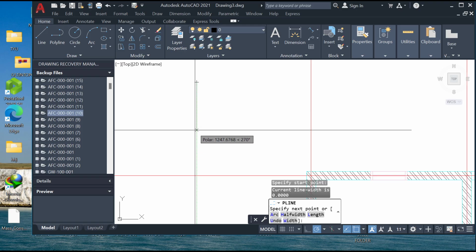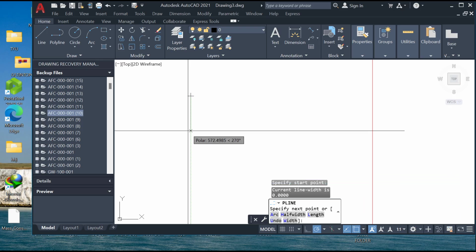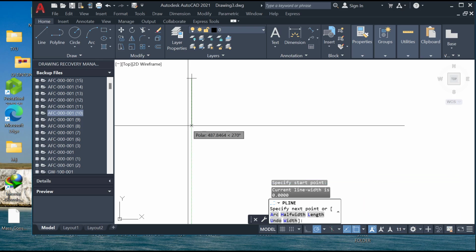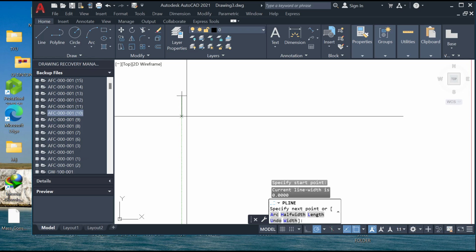For Nigeria, the width of the block work is 225 millimeter, and that is why we are using a column of 225 by 225, because the column has to be hidden inside the wall.